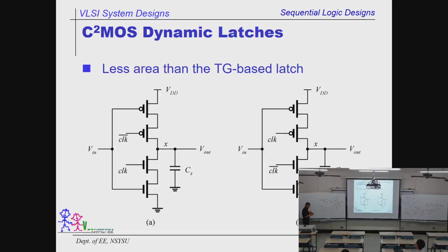Now this gives us another risk. That is the slope over here, they are not that straight. From time to time, they are slanted. So is the clock bar. So there is a risk. There is just a little bit of risk that both of the transistors will be on. That is what we are worried about.